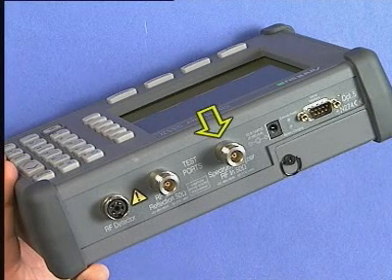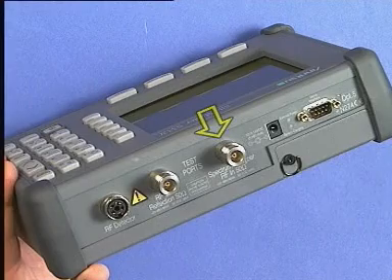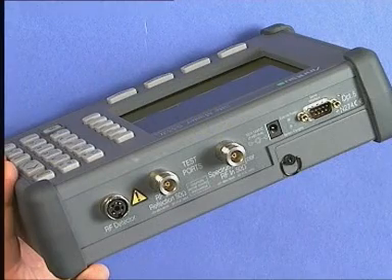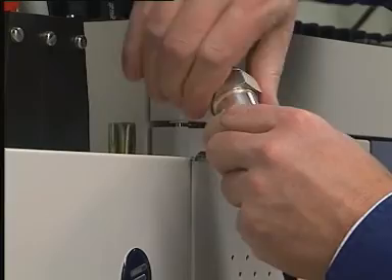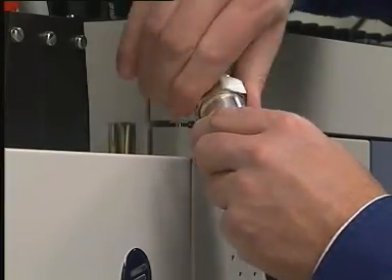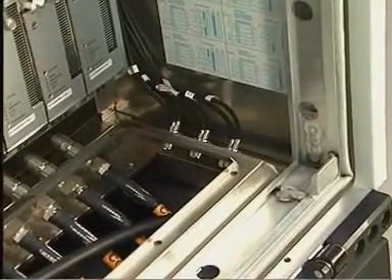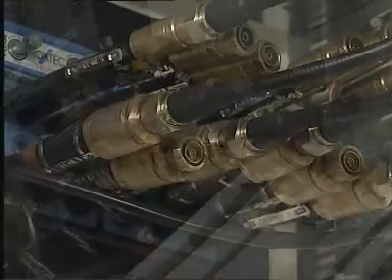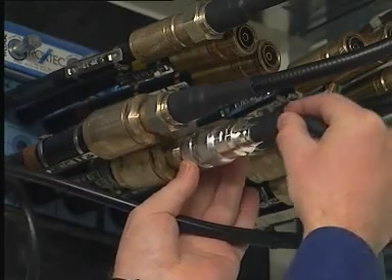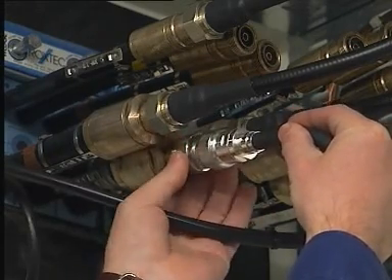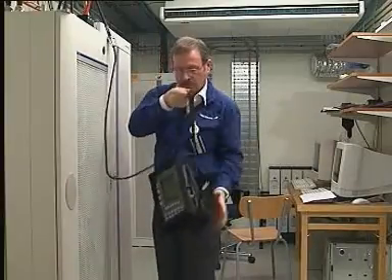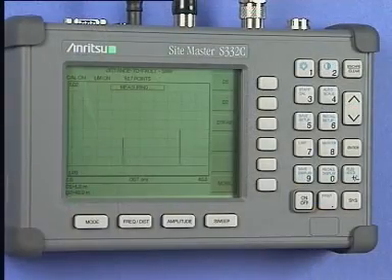Connect the Sitemaster's extension cable to a spare antenna. You could use a spare antenna from the radio base station, a convenient receive antenna outlet, or another antenna that is not in use. We are not really too concerned about the actual signal level, just to identify it and decide if it is excessively strong.